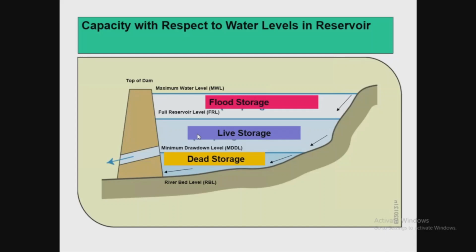Otherwise, what will happen? Sometimes the reservoir's live storage is encroached by 50%, and you will not come to know. Because from the top of the reservoir you will see that a lot of water is there, but actually it is encroached by sediment. So it is very important for civil engineers, especially academicians and researchers, to assess the capacity of each and every reservoir, and it is essential for government officials also to get this capacity surveyed at least every 3 years, or at least every 5 years.